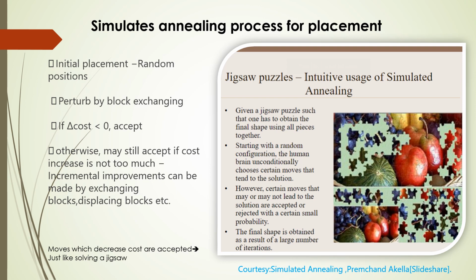Just like what you see in the figure, we start from the initial placement or random position, and then keep on changing by block exchanging or swapping, such that if the blocks are exchanged and it results in lower cost, then that movement is accepted.